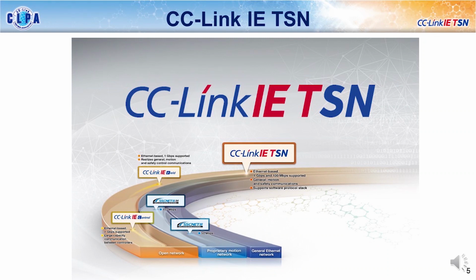TSN is an extension of standard Ethernet that regulates data communication, making it deterministic, providing the ability to combine different types of traffic on a single network. This is called convergence, and provides the foundation of process transparency required in Industry 4.0. CC-Link IE TSN is the world's first open industrial Ethernet technology that combines a gigabit of bandwidth with TSN technology.